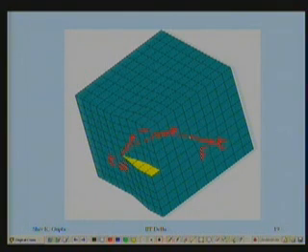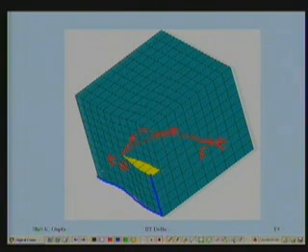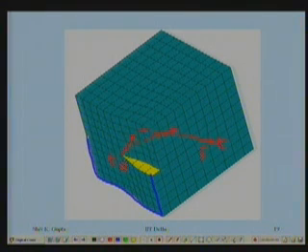If I take this T vector, which way shall I draw the Burgers circuit? Around this point, clockwise. Good. So what I do is I draw a clockwise circuit. I will not put anything counting. You can count these steps. It's exactly the same way we did earlier.